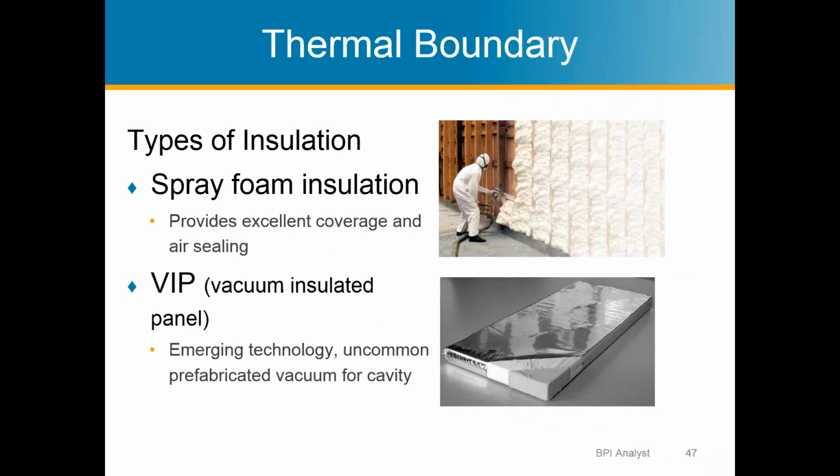And then spray foam insulation, that's kind of all the talk in building science still for like 10 years now. There's so many great things about spray foam insulation, the R per inch, and spray foam insulation is a generic term. It's like talking about soda pop. There's all different types. There's closed cell, there's open cell, there's different manufacturers. There's some that's got a soy base, as they call it, but there's a little bit of soy in it. Most of them are all largely petroleum.